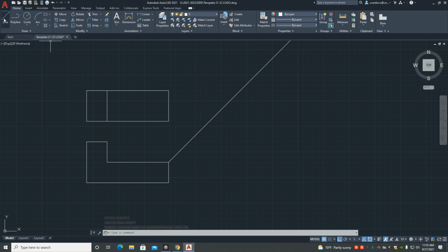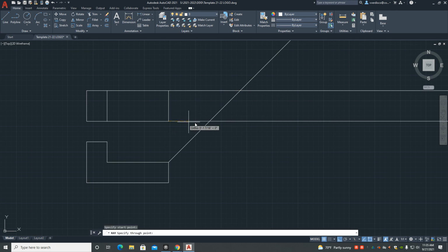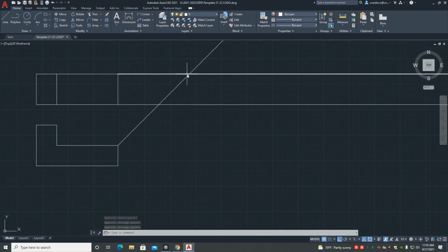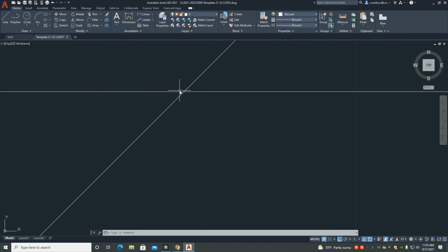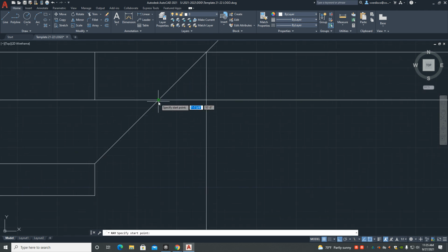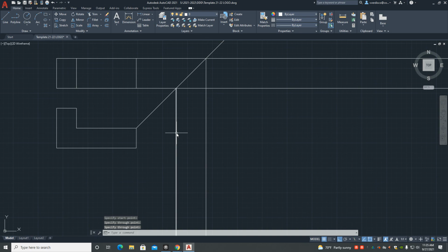So let's go ahead and get the ray tool again. We're going to go straight across like this and straight across like that. Now, do you see where it crosses over? These lines cross over each other. Wherever they cross over, we need to go straight down. Think of it like a laser hitting a mirror. So again, I'm going to get my ray tool, and right where it meets up, click and drag down. And again, we're going to click, drag straight down like that. So now we've established that 3-inch gap here by borrowing it from here and bringing it down.